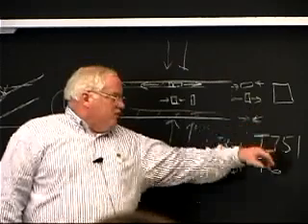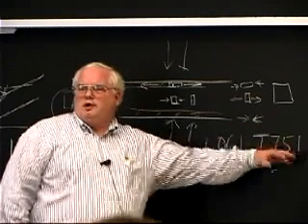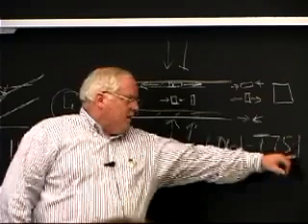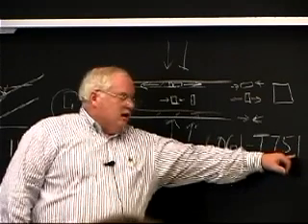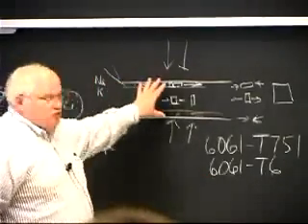T7 is a slight overage, and the 51 means 1% elongation. Okay, the 5 is in there for something else. I can't remember why. But it means that they actually stretch the plate 1% to relieve the residual stresses.